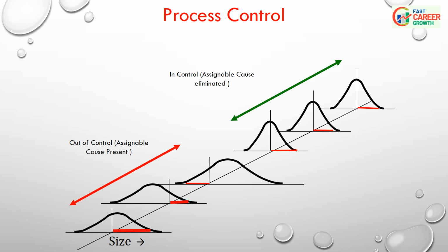Simple statistical process control techniques can detect special causes of variation. Discovering a special cause of variation and taking the proper action is usually the responsibility of someone who is directly connected with the operation. Although management can sometimes be involved to correct the condition, the resolution of a special cause of variation usually requires local action, that is, by people directly connected with the operation. This is especially true during the early process improvement efforts.